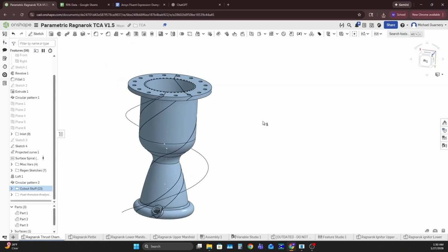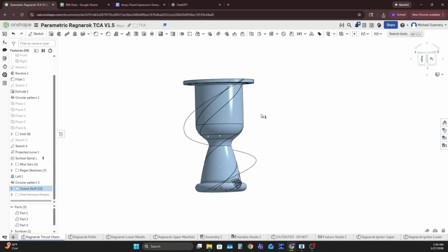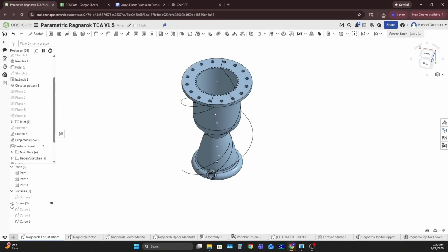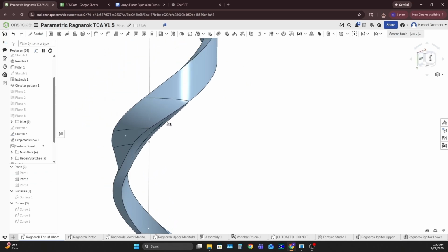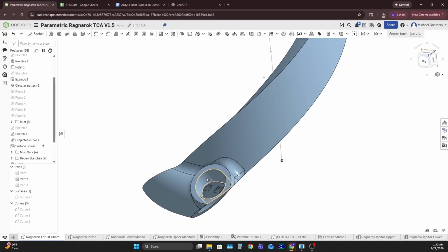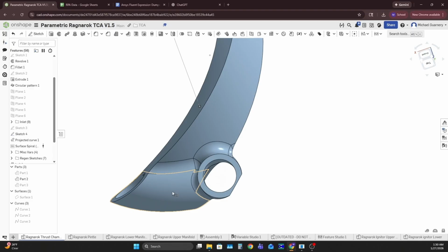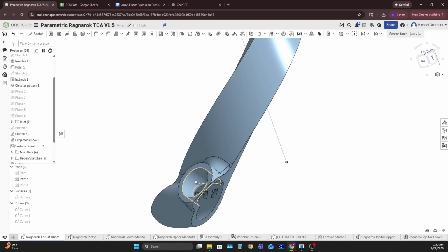So the cutout folder will make a 5-section cut that we can then also download and bring into Ansys later on. So if you come down here, let's first make sure that all of our curves are hidden. Then let's hide part 1 and hide part 3, and we have just our 5 sections of our regen channels. The next thing that we need to do is we need the inlet to be centered in the middle of the bottom of the fuel annulus so that we can still inject our fuel into this inlet.